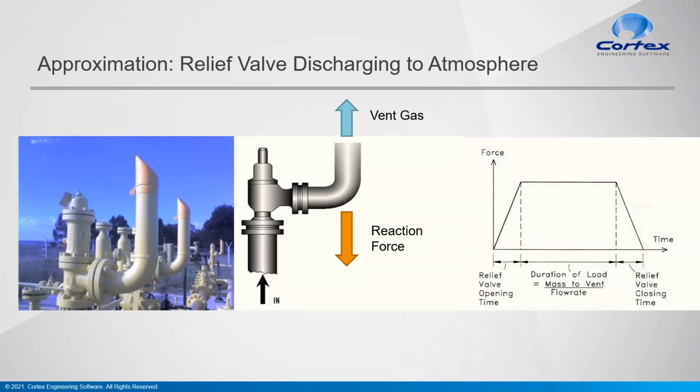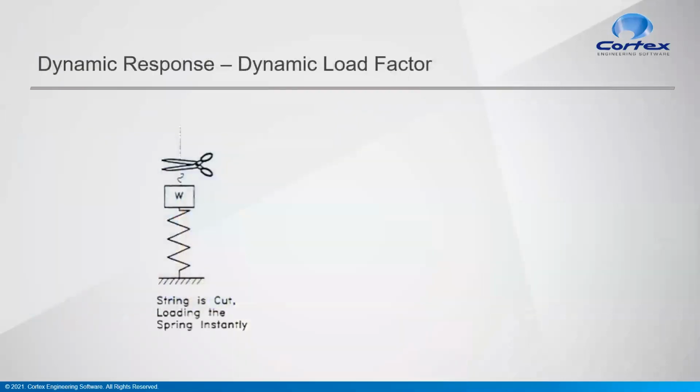And that reaction force obviously starts off as the valve opens, maintains for a period of time while the valve is open, and then drops off to zero as the valve closes. And we have some fairly well-known formulae for calculating the reaction force, which involves the ratio of specific heats and the pressure and temperature of the fluid. But I think, as most people dealing with dynamic relief valve systems would realise, that's not the end of the story. We have to consider the dynamic response of the piping system.